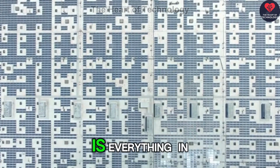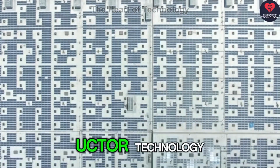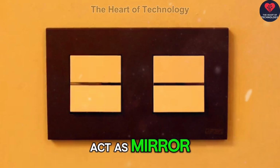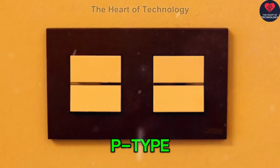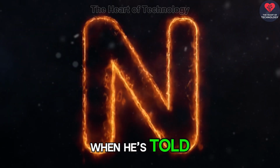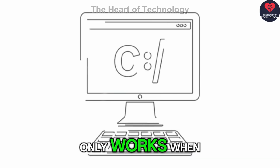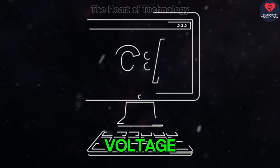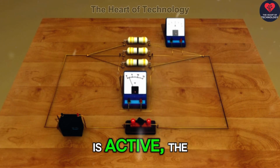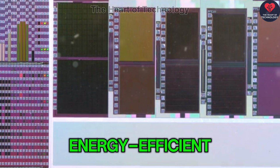In nature, balance is everything. In computing, we achieve balance through complementary metal oxide semiconductor technology, or CMOS. This involves two types of transistors that act as mirror images of each other, N-type and P-type. Think of them like two different types of workers. The N-type worker is eager. He works when he's told yes, high voltage. The P-type worker is the opposite. He only works when he's told no, low voltage. By pairing them together, we create a push-pull mechanism. When one is active, the other is resting. This symmetry is what makes modern chips so reliable and energy efficient.